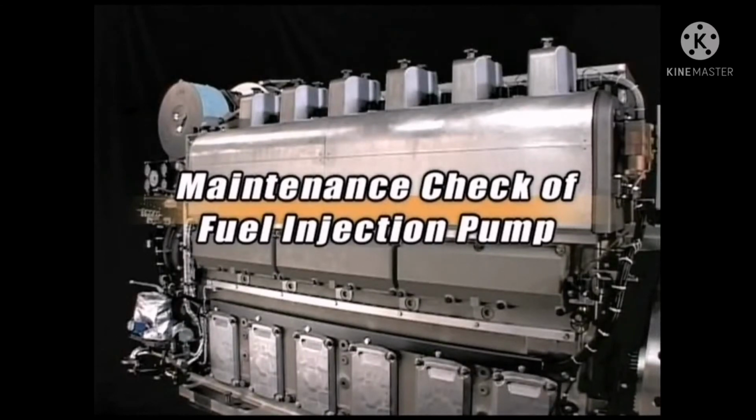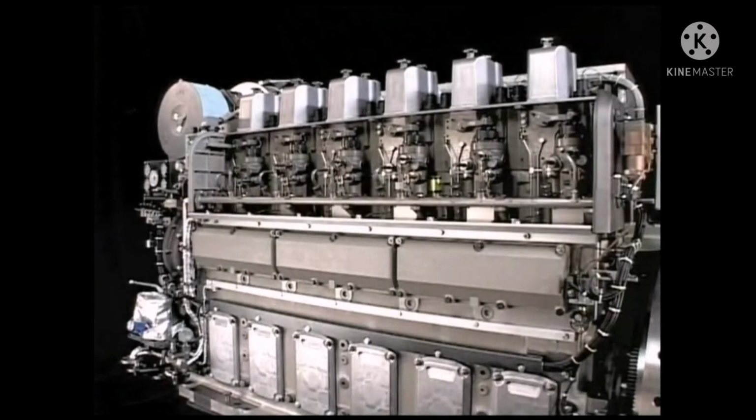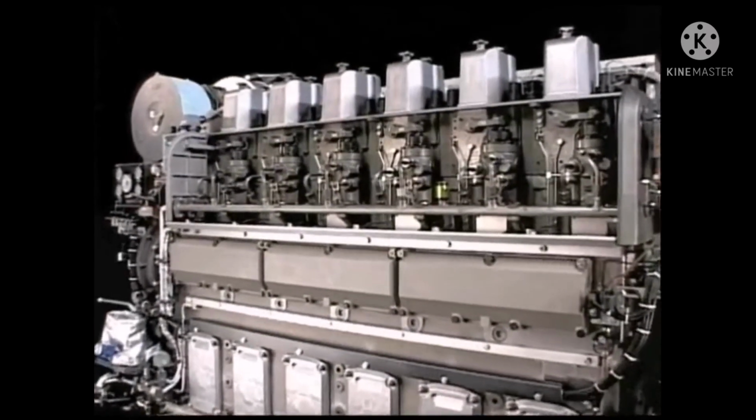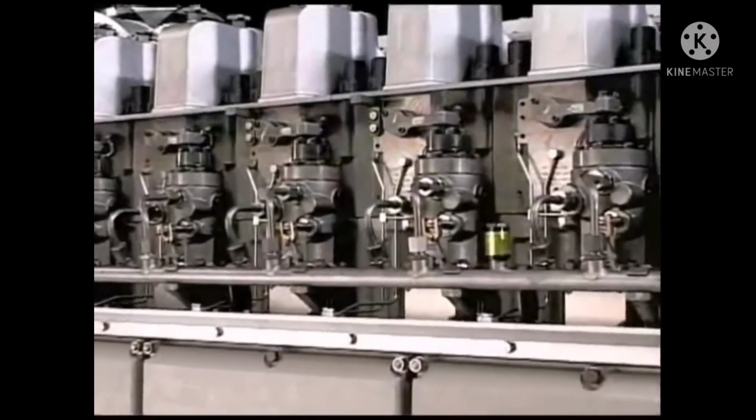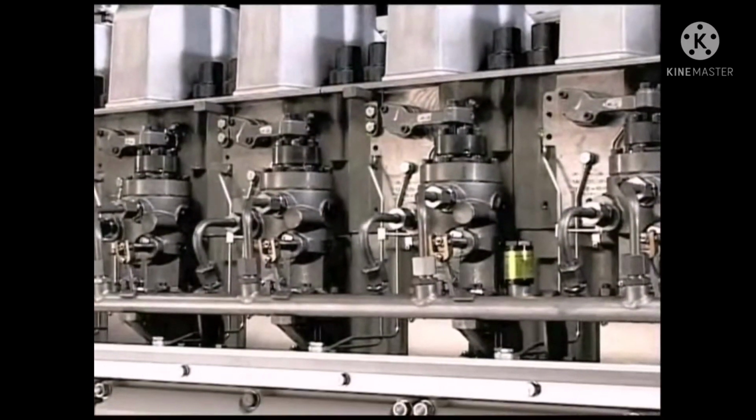This is the explanation for daily maintenance check of the fuel injection pump. Check the rack graduation and the oil quantity of the pinion at every 300 to 500 hour interval. I will explain the procedure.